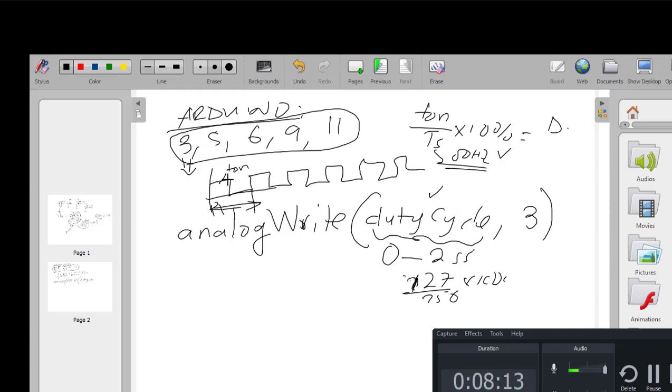But the way we are doing it right now is that we're trying to show you that whatever is going to be the duty cycle sent to pin 3 depends on the value that you're actually loading. In this case, if we looked at the Arduino ATmega, you could see that that was the output compare register value if you're running it in CTC mode.